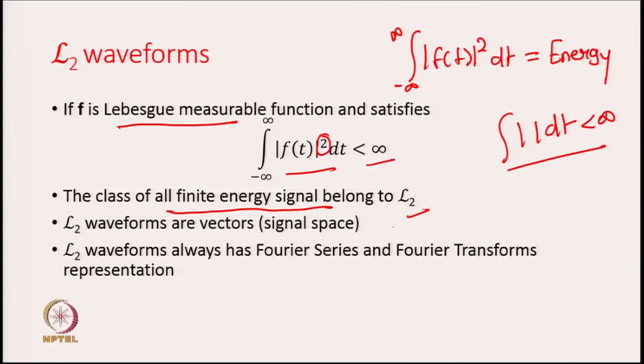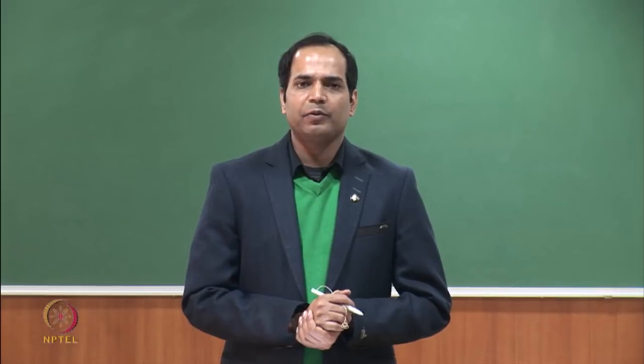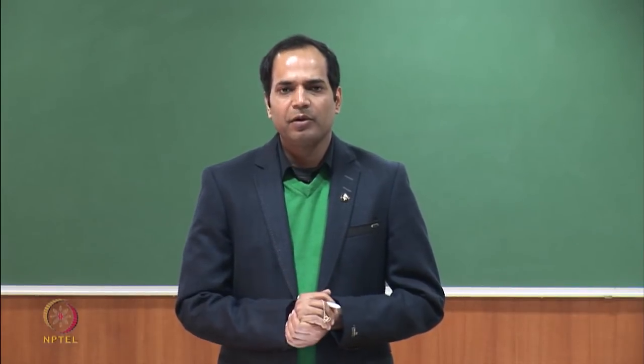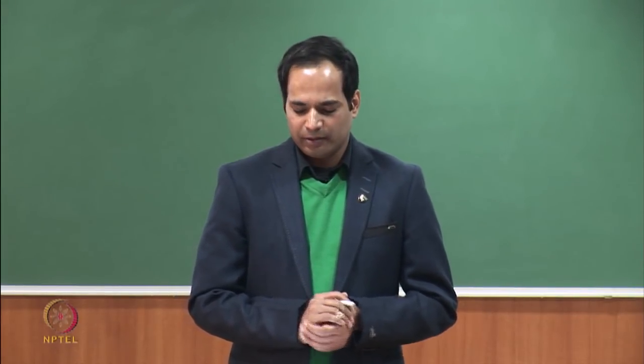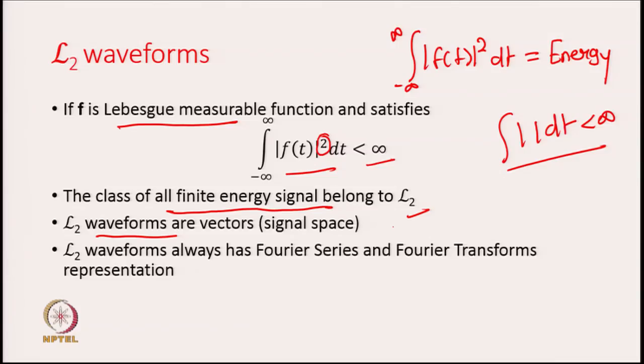But mathematically we would be interested in certain functions which have infinite energy, and thus we have to be really careful when dealing with those signals. Okay. Now, one important advantage of L2 waveforms is that they are vectors. You can treat L2 waveforms as vectors and use the ideas of signal spaces. Secondly, L2 waveforms always have a Fourier transform and Fourier series.